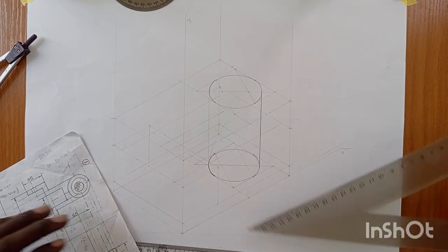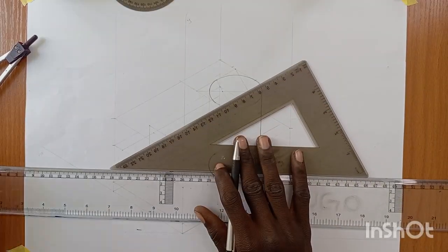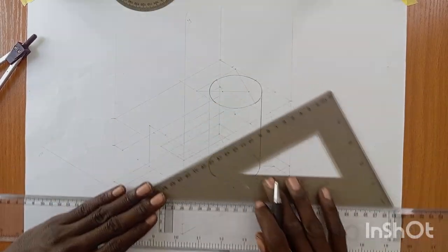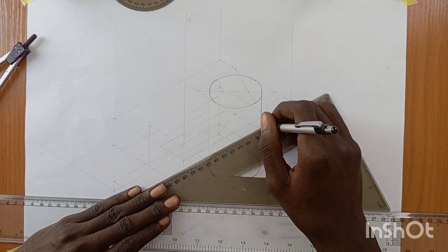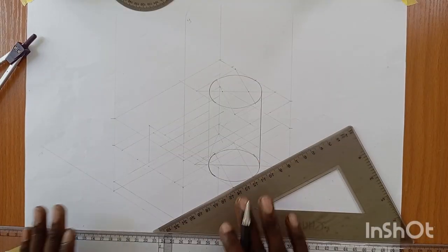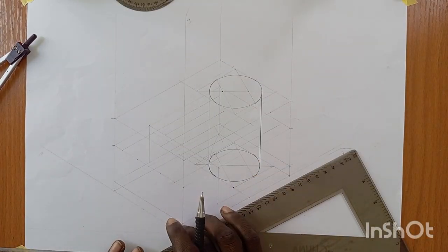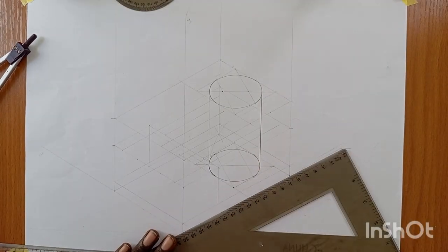So now to do that, I'm going to make a mold line. Let me do a construction line here also, for I will now do the mold line. Whenever I touch the cylinder, that's where you are going to stop. For this one, I'm going to take it inward, just take it to the cylinder. And now let's darken the spaces to see our drawing more clearly. Now we can start with the base here, and let's darken this place.